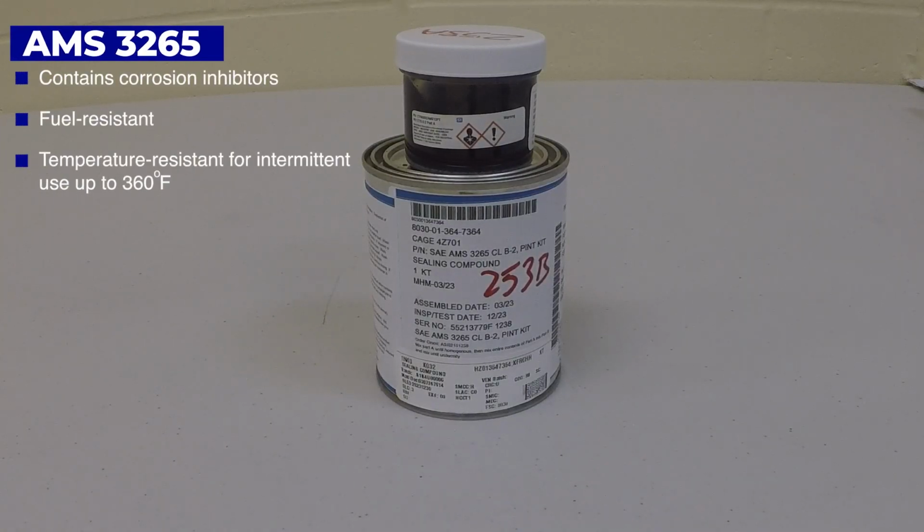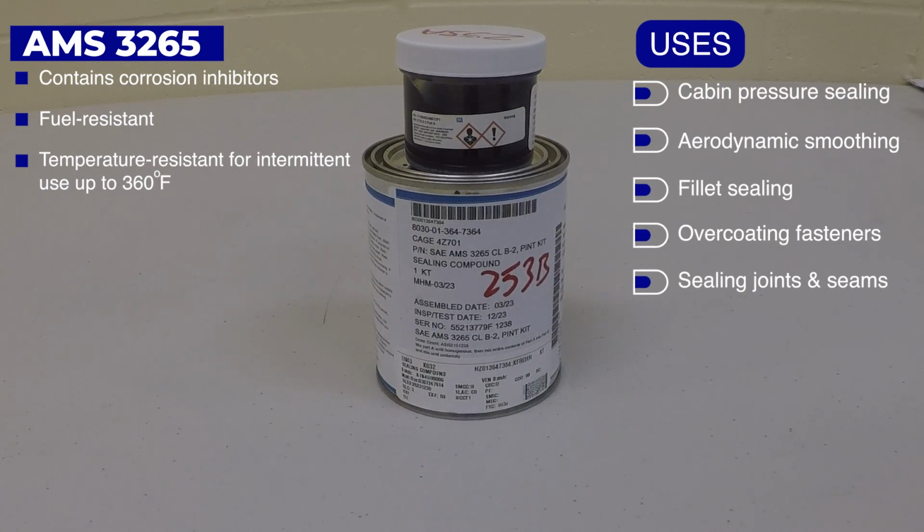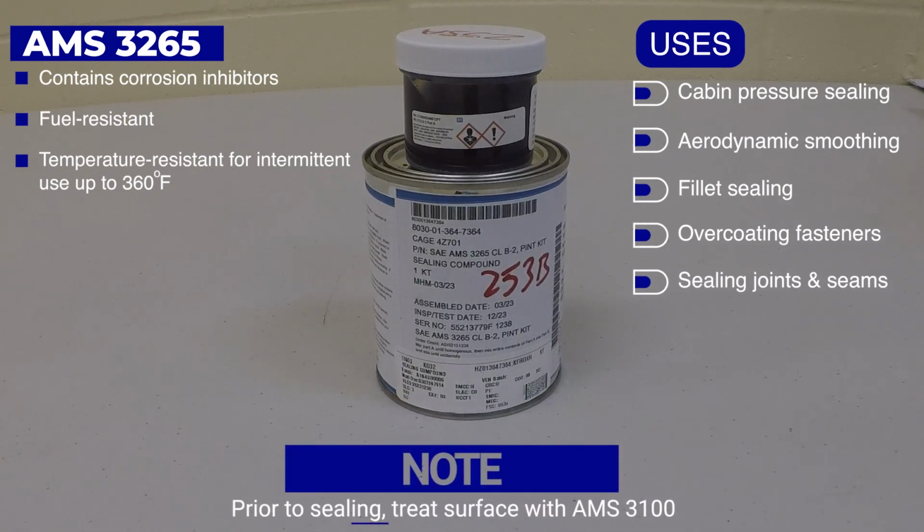AMS-3265 is fuel resistant, used for intermittent uses up to 360 degrees Fahrenheit, cabin pressure sealing, aerodynamic smoothing, fillet sealing, overcoating fasteners, and sealing joints and seams. Prior to sealing, treat bond surfaces with AMS-3100 adhesion promoter to enhance sealant adhesion. Contains corrosion inhibitors.